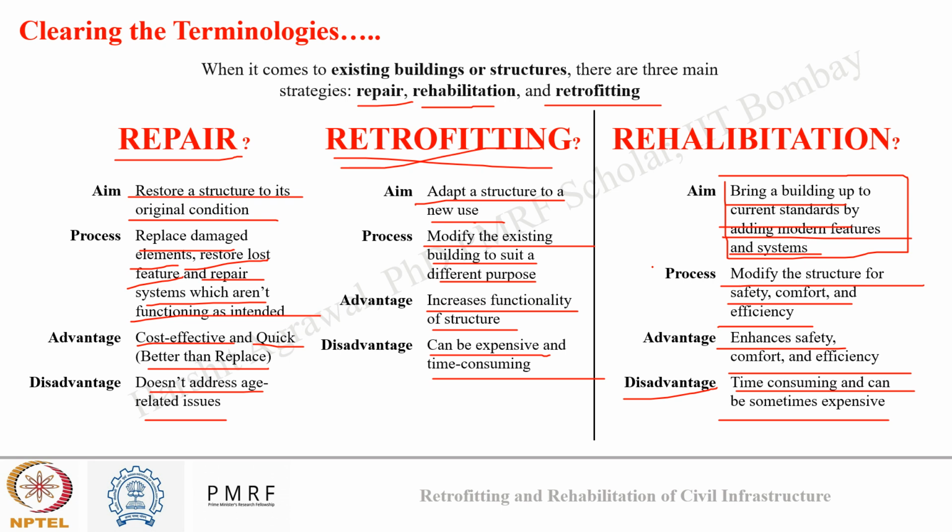Okay, and rehabilitation is carried out when the guidelines regarding the use of the structure have changed. Okay, so now we know when we need to think about repair and when we need to think about retrofitting, and how it is related to durability and strength. So by remembering and understanding this, one can have a good judgment on site also, seeing the condition and the testing result, which way to go forward.